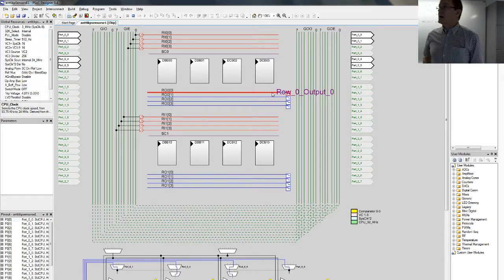These blue lines, each of them is 1 bit on a nibble, that can then be connected using the global output lines on the right hand side to those corresponding pins. It looks a little bit complicated, but when you get the hang of it, it's actually quite flexible.